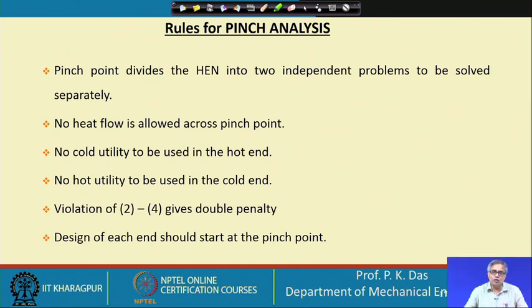I do not recall whether I have told this or not, but it is very important and has to be kept in mind. Design of each end should start at the pinch point. These few messages, they are not only information, they are very important rules that we have to keep in mind.